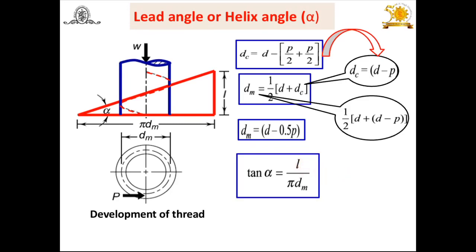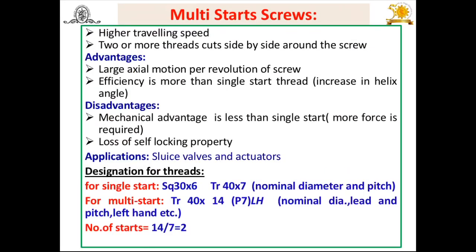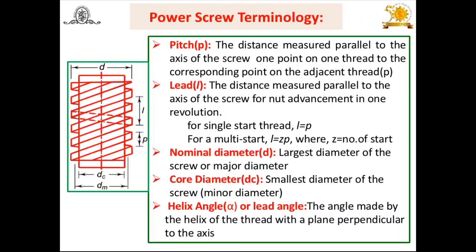Again here, in single start and multi-start threads, the important point is: for a single start thread, the lead is equal to the pitch. But for a multi-start thread, the lead is equal to Z into pitch, where Z means the number of starts.